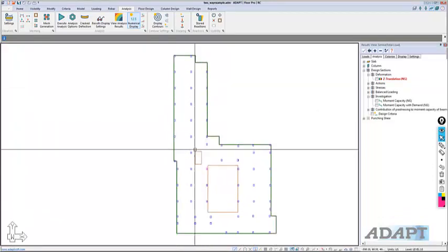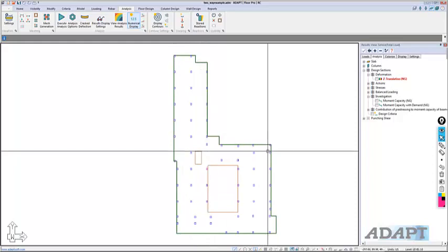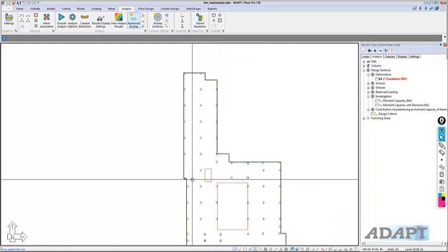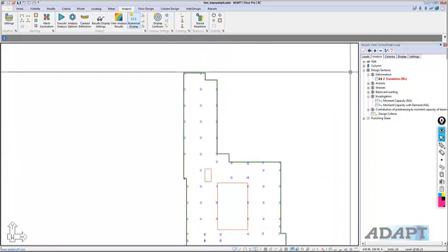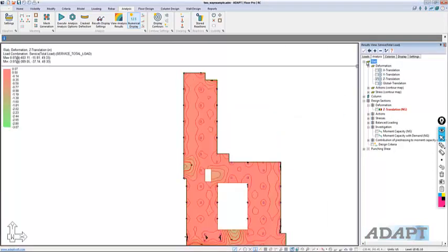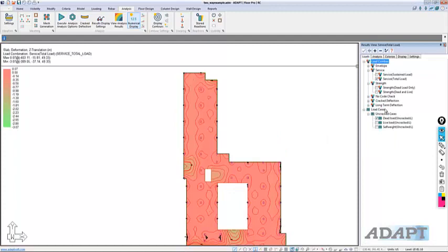This crack deflection check, maybe the output is not, let's say, complete, only because we haven't calculated rebar in this zone. So after the crack deflection check has been run, if we go to the slab deformation under the Z direction, we're going to go to loads, and for crack deflection we have the deflection assuming I gross and the deflection assuming I effective, and this would be the cracked deflection.